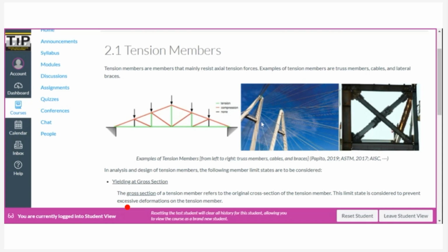Okay. And then we also have the bracings in a building. So for example, if a building is subjected to a lateral force, for example, if you have a cross bracing right here, this bracing may undergo axial tension, while this particular bracing here may undergo axial compression.